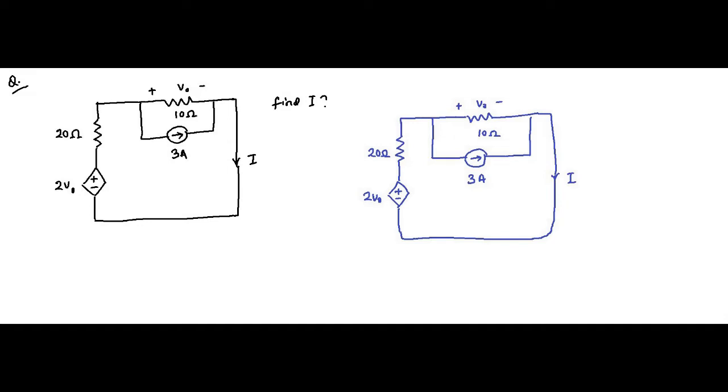First, the important thing, the voltage dependent voltage source here, this is the important parameter. Now let us try to figure out how we can solve the circuit. So the way I see it, it will be easier to use the KVL approach to solve this circuit. So here, let's say this is the current I flowing from here.